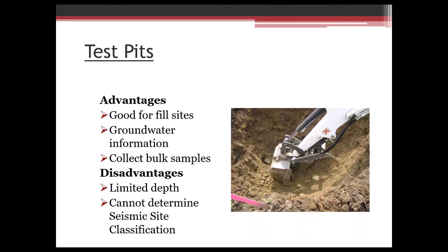We're generally only taking samples with a 2-inch split spoon, so it may not get a good representation of that fill, and we may see some organic material, but we may not realize that it's maybe all organics, or maybe there is just a little bit of organics, where digging a test pit allows us to be able to see that information better. For certain types of projects, it can actually give us better information on the groundwater.